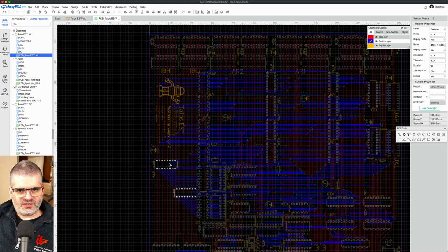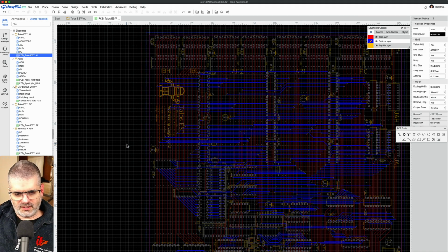Branches will not necessarily cause reflections. They will just worsen the reflections in the sense that each branch will have a certain resonant frequency different from the others. So there will be more reflections, each one corresponding to the resonant frequencies of each branch. But hopefully these two resistor networks here will absorb the brunt of it. And there won't be much of a big deal with that.